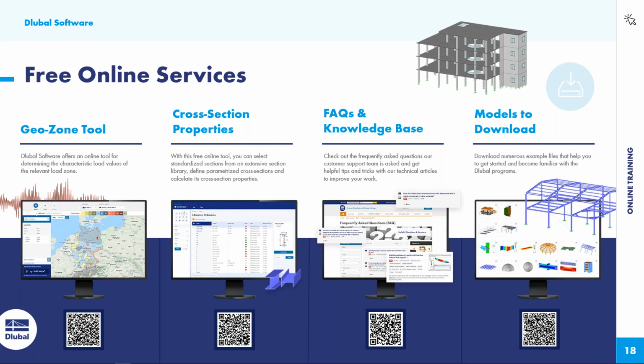We've covered basic beam theory and plate theory, compared them. You know now the difference between the Kirchhoff and Reissner-Mindlin theory. And you also know that Reissner-Mindlin is the better theory when it comes to thick and massive slabs and plates.